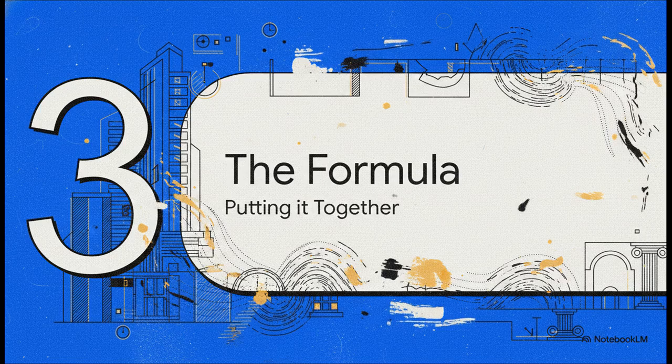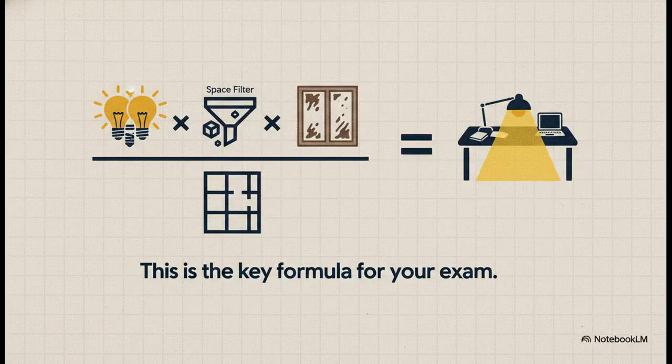So now we get it. We have our two filters. We've got the space filter, CU, and we have the time and grime filter, LLF. It's time to put them together in the one formula that you absolutely have to know. And here it is, the lumen method. It might look a little scary, but it's really just the story we've been telling this whole time.